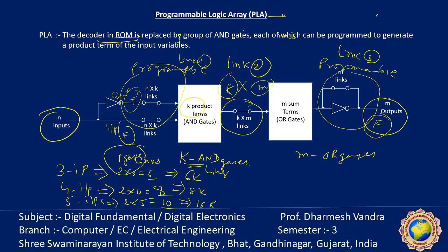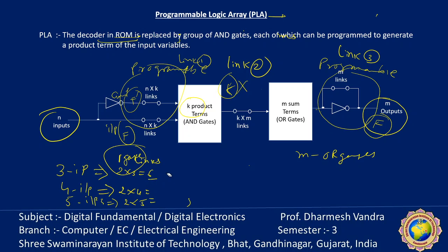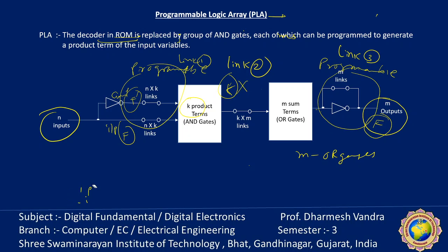It depends on the complexity of the function, so the output function is to be generated by AND or invert, any one of these things. If the inverter link is in place, the inverter is bypassed, giving an AND-OR implementation. Suppose I just open this link, it will become F dash. If I connect this link, it will become F, and this gate will be bypassed. So here the first question is generated: how many total programmable links are there in this configuration? The main point is that there are 3 stages of links. First is at the AND gate input. Second links are at the output of the AND gates, and the third links are at the output of the OR gate to bypass the inverter or consider the inverter.